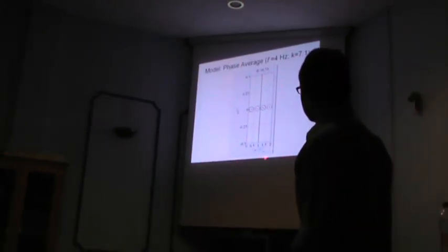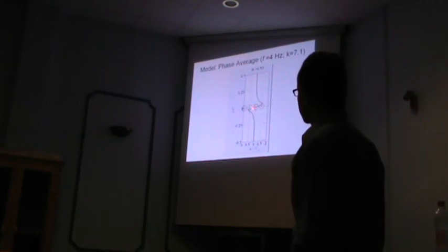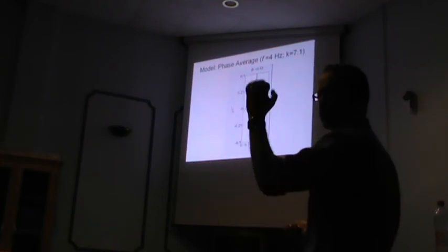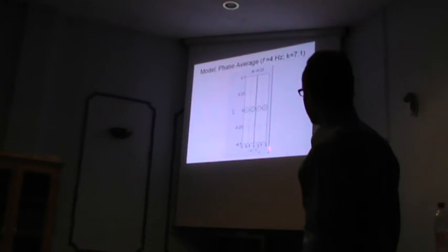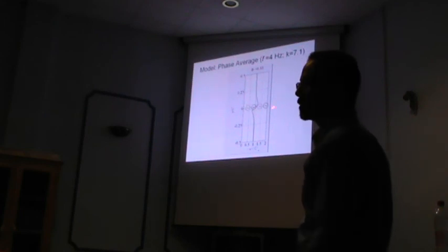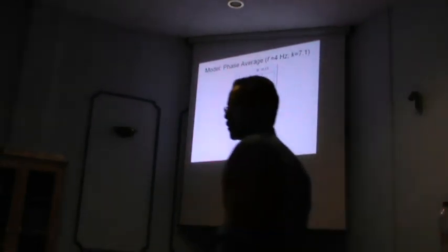So this is the computed velocity across the wake. You see here the train of vortices going by, where in this case black is negative and red is positive. And notice how when a vortex coincides exactly with the position of the calculation, we get the highest shear, which is induced by this vortex going by. Now, because in this case the vortices for this neutral condition are aligned on the center line, whatever the positive vortex does is exactly cancelled by the negative vortex, so the net effect is just uniform velocity across the wake. And that's how we get the neutral condition.